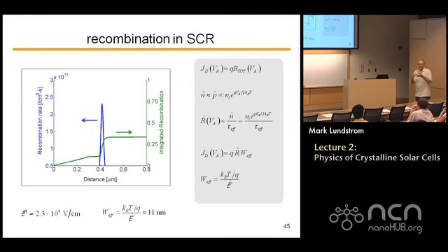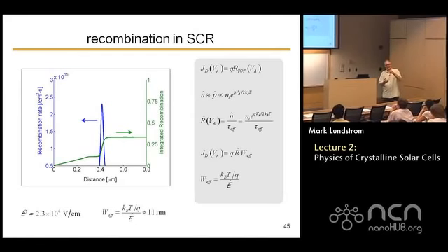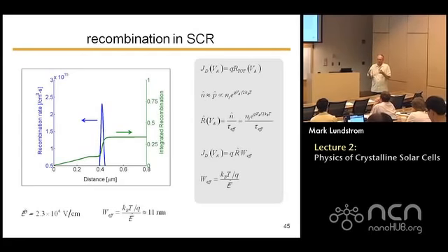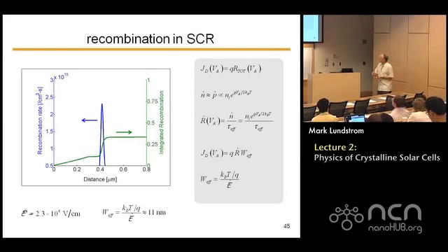It's not a bimolecular one, right? The electron is falling down into a trap. Now, when you have a radiative recombination process, you need both an electron and a hole, and they recombine together, and the recombination rate is proportional to the product of the two. In this case, you have a trap that's collecting one, and a trap that's collecting the other, and the rate at which electrons recombine is the rate at which that whole process occurs.